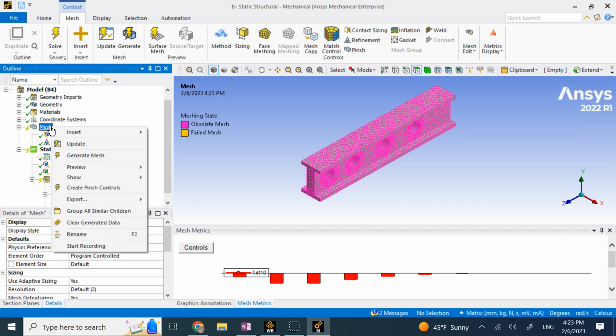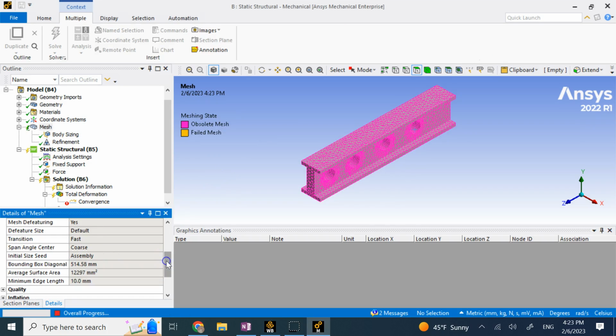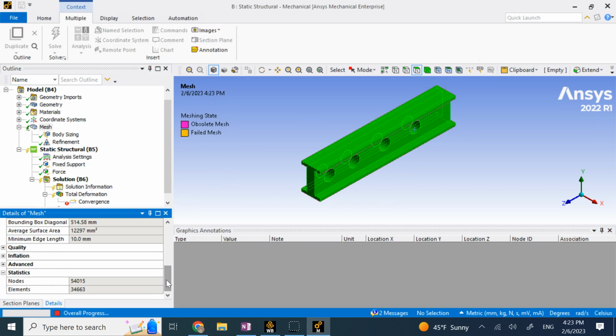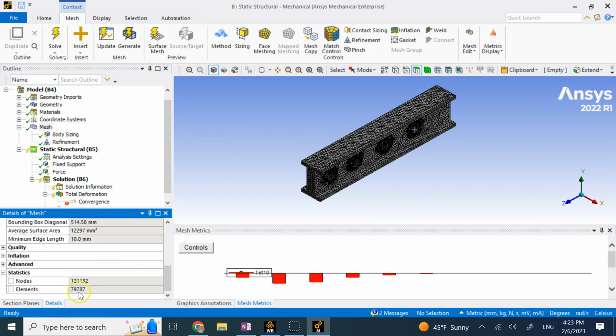Now you can calculate it exactly, because it's a cubic factor. When you are changing the size down by a cubic factor, the volume would change and the number of elements. But here I'm just doing some rough estimate of what global size might be good in this case. And let's just see here, I'm at 79,000.